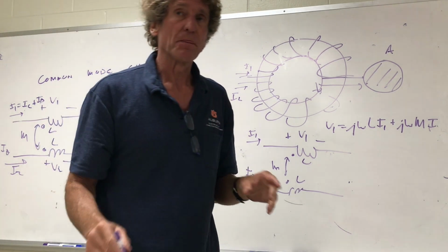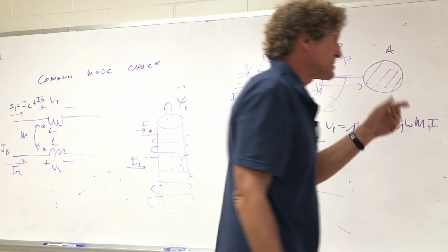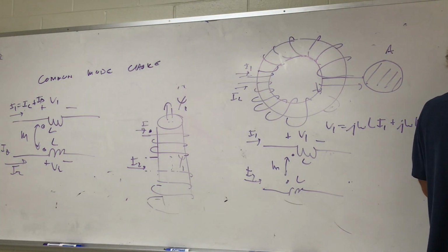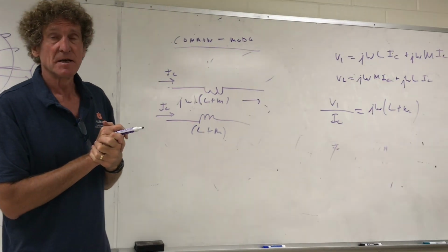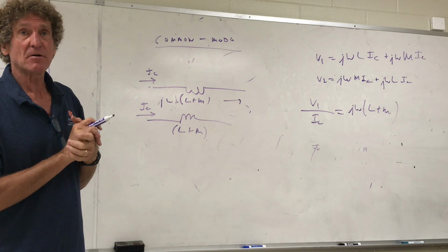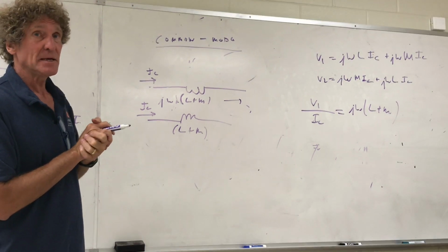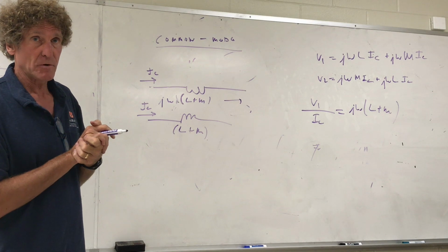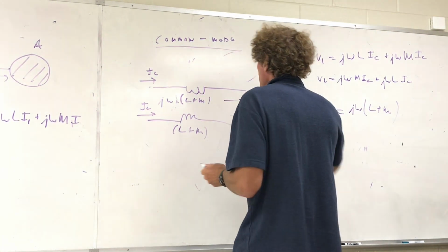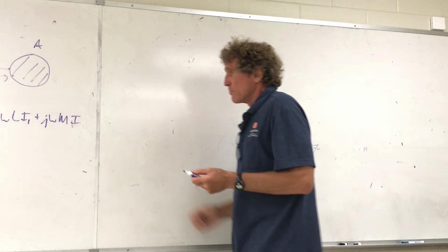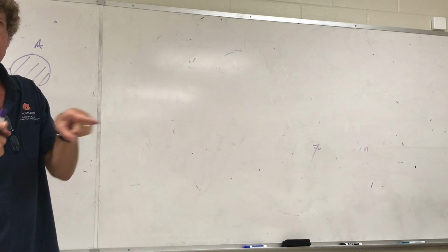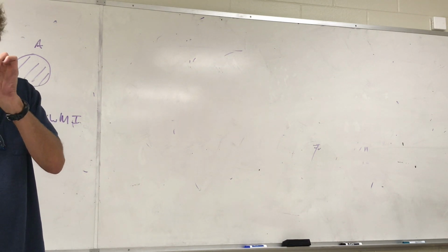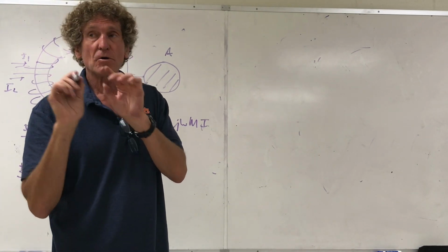You only want differential. So the impedance of this would be j omega times this. That can be huge. If you're talking about frequencies of like 10 or 12 megahertz or even gigahertz, that impedance can be huge and it can block a lot of the common mode current. That's what you want. Now when we do differential mode, this is in the book. If you're going to block common mode, you want to allow differential mode, because that's the way things work. When you have an extension cord, current goes down one leg and returns on the other wire, same magnitude, opposite direction. You want to allow that.